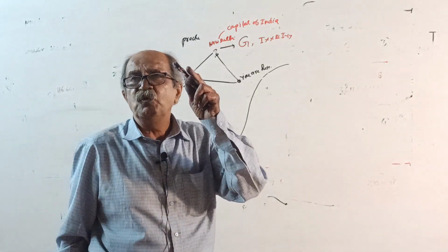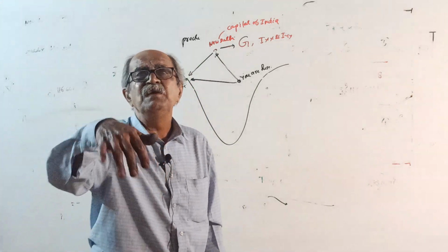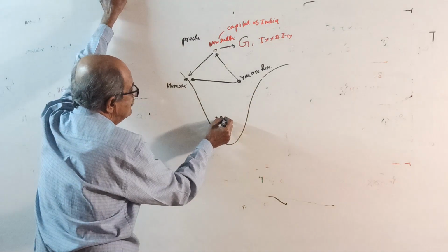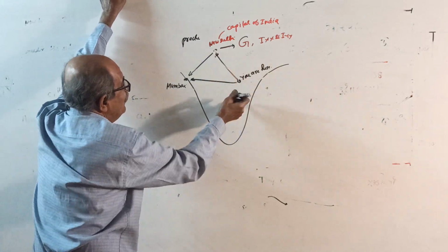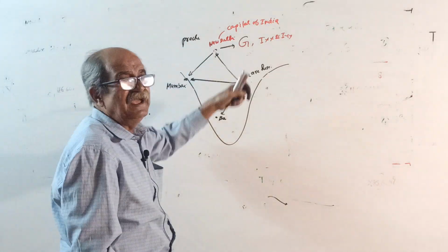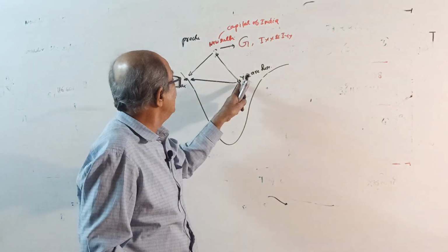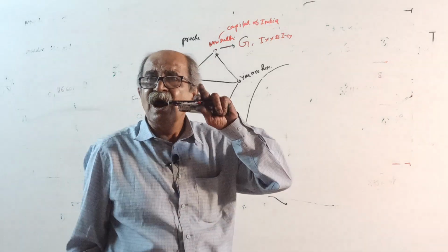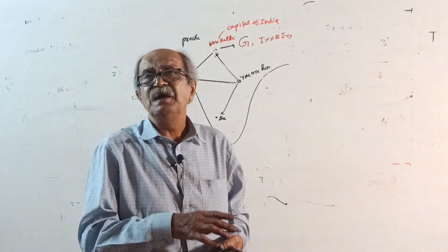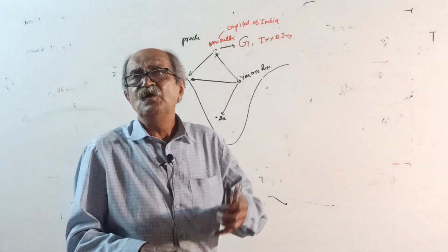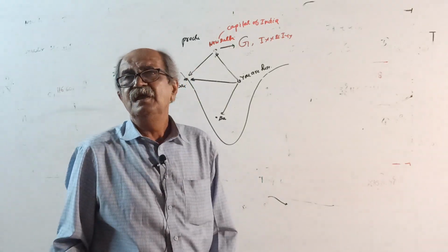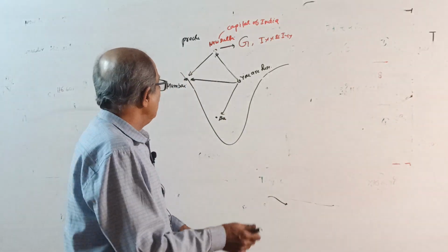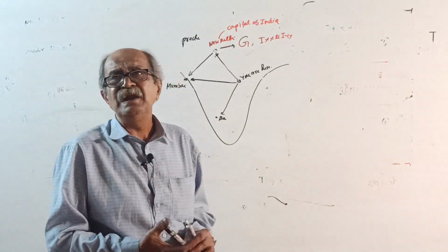But if the question is to find the moment of inertia about a randomly given axis, suppose someone tells you, go to Bangalore. Don't go to Delhi and then come to Bangalore. Directly come to Bangalore. From there, take a flight. Flights are there everywhere. Therefore, if you are asked to find I about the centroidal axis and also about some other axis, first find it about the centroidal axis, then using that, find I about the other axis. But if you are asked to find I directly about some other axis, then directly mark those axes and find the moment of inertia.